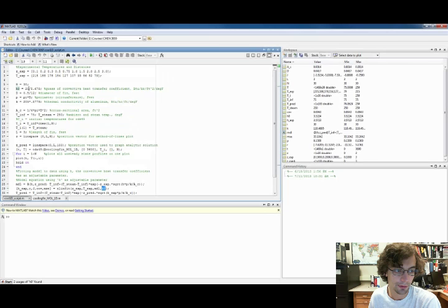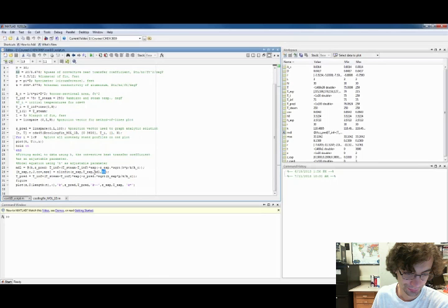These are your data points that you collect experimentally, and you include your model, and you give an initial guess of h, the heat transfer coefficient, which I provide further up here in the code, as I just picked 20. It's kind of a guess, 20, but divided by this unit conversion because I'm doing it in English units.